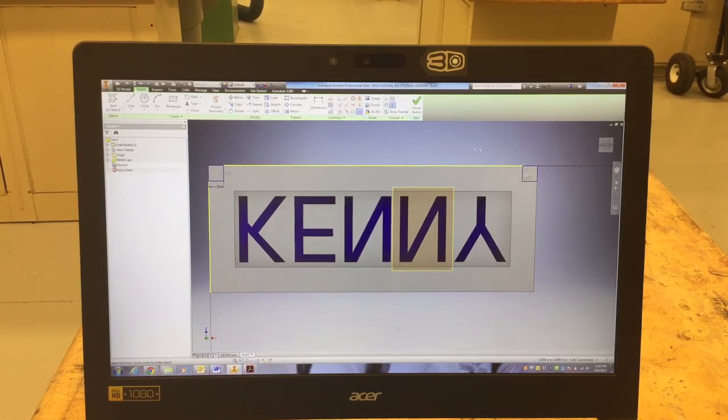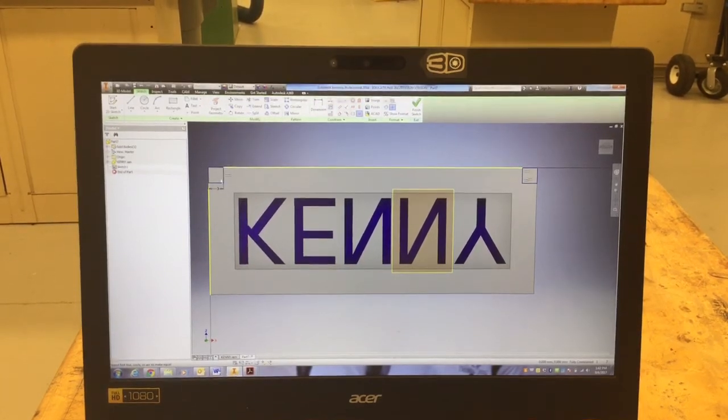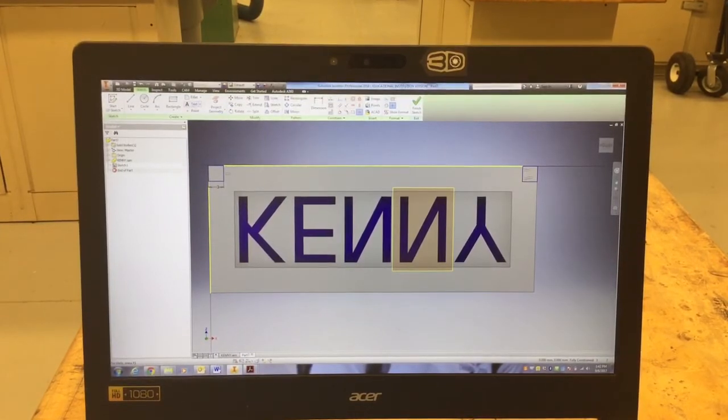If I didn't want to do this, I could just use dimensions like I've always had, where I would dimension every single line to be 3 millimeters. The advantage of doing it this way is if I ever need to make a change, if I change just one, I've changed them all. I had to do that when I originally created this because the first time I made it, it didn't work out right. So this is going to be 3 also. So I made 3 or 4 rectangles that are all the same size in the very corner of my box.